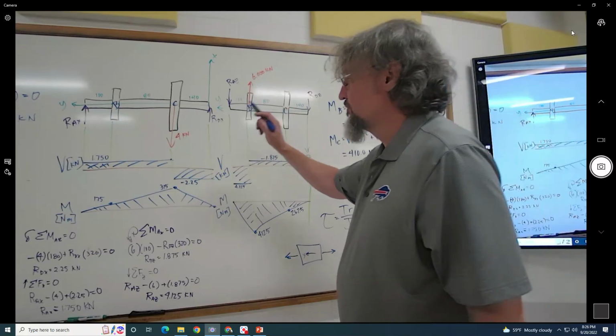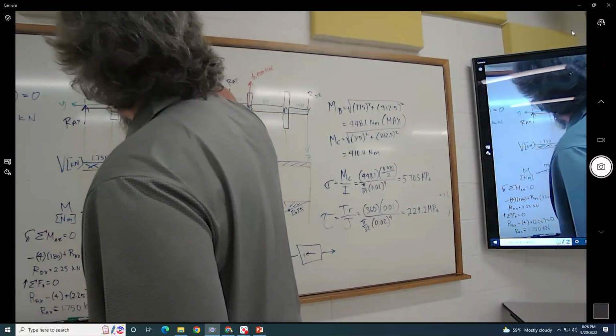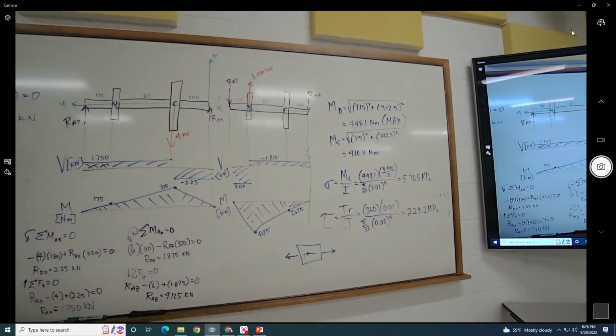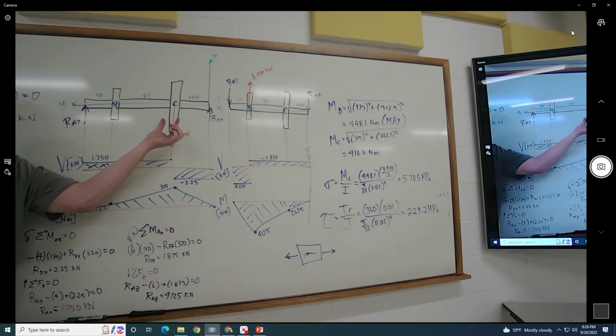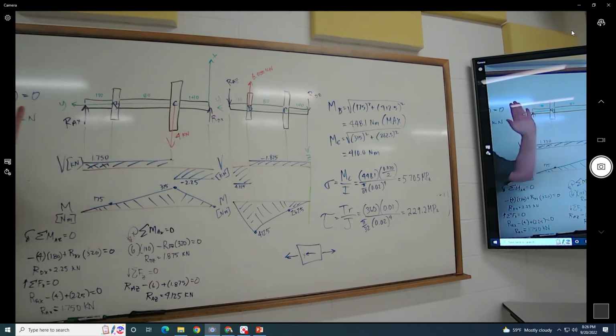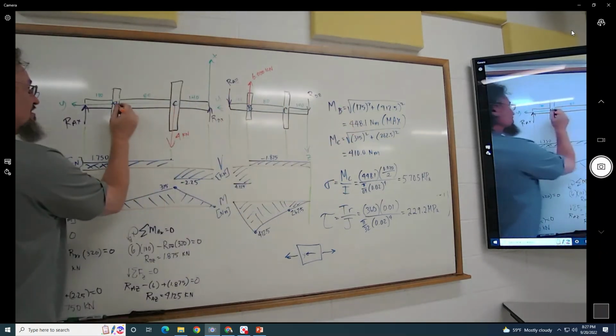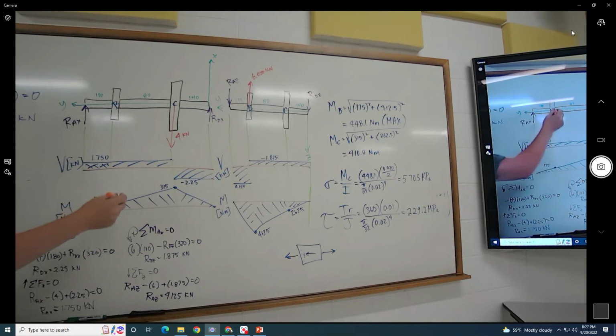Now, the torsion, we should point out, is only between these two pulleys. It only exists between here. I'm not sure where I usually say this in the semester, but we want to deep dive and really look at the thing. This is an approximation because these pulleys actually have a width to them. So we're making it fast and ignoring their widths, and we're saying there's going to be a stress element, and we know that it's going to be at B. So there's a stress element somewhere really close in there where it's going to have both the torsion and the bending stress.